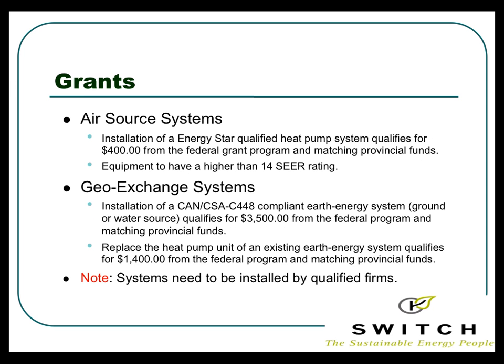Geo-exchange system, of course, though, gives us an even better performance because that air source heat pump is going to give us, say, 2 to 3 times, 200 to 300%. Okay? We move up to geo-exchange system, now we're up into 400% efficiencies. We can reduce your cost of operation upwards of 66%. So save 66% of that fuel cost. But recognizing that the cost on that system can be upwards of 5 times. And that's really dependent on, are we able to put in that horizontal loop? Or what are we drilling into if we're doing a vertical bore? Okay.